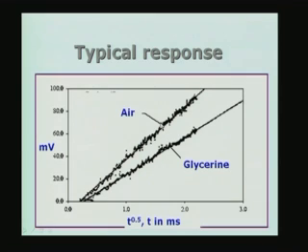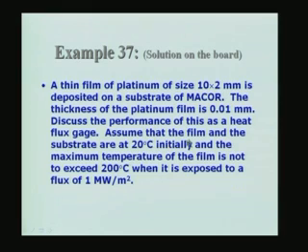The experiment has been conducted in two different media, air and glycerin, and you can see in case of glycerin the heat transfer is much more rapid, and therefore you have a smaller slope for the line, whereas in air it is a larger slope.